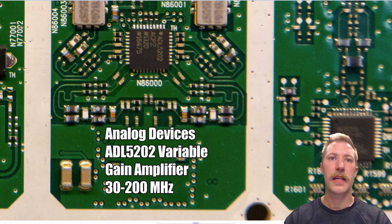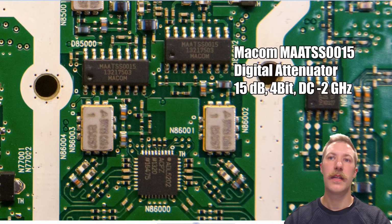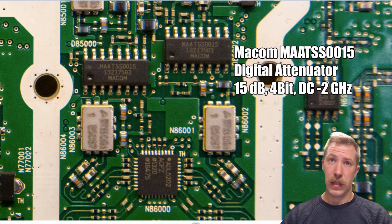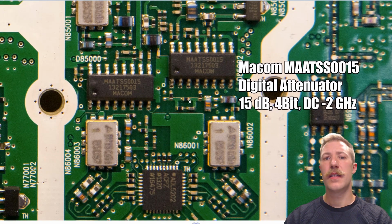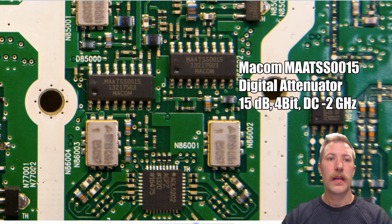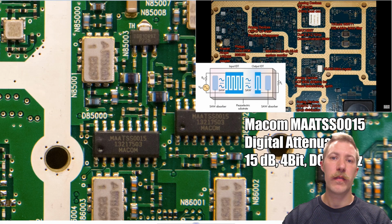As we can see, it has dual input lines, and it has surface acoustic wave filters sitting along the line before we get into the digital attenuators. So here we can digitally adjust the signal strength to suit the impedance of the amplifier, or actually just adjust the signal to the load on the amplifier so as to lower the reflected energy back from the antenna. About the surface acoustic wave filters, I also did a detailed video on that, so there will also be a link to that video in the description.